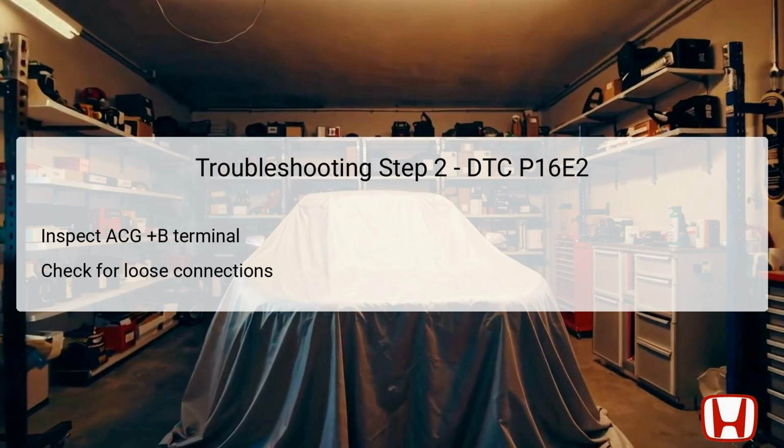When checking the terminal, ensure you examine both the physical condition of the terminal and the wiring connected to it for wear or damage. Once the terminal is secured properly, the system should be powered back up to see if the DTC reappears.